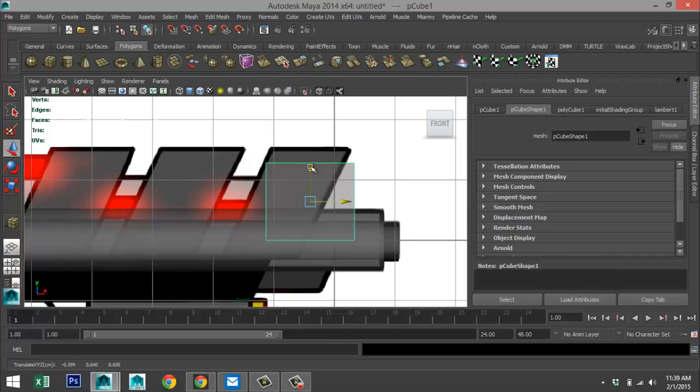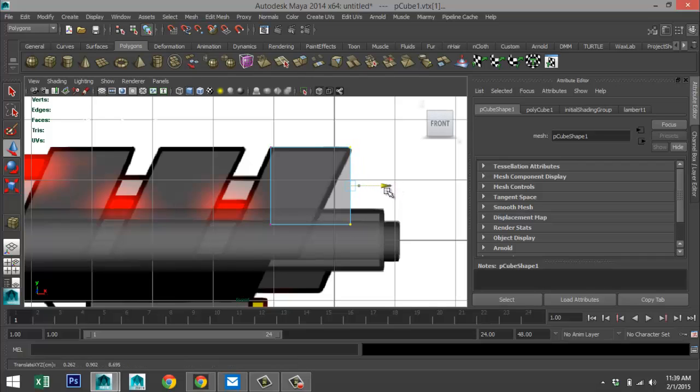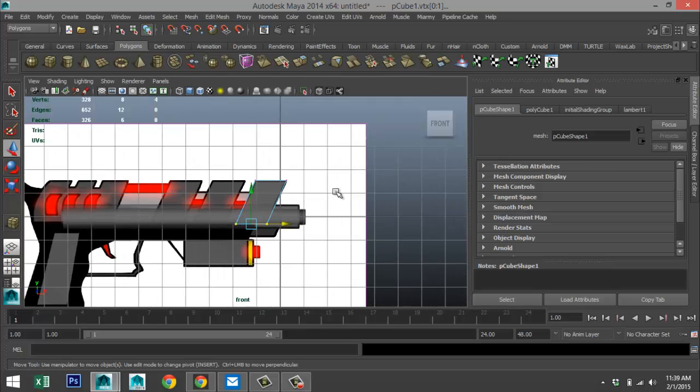So there it is. Hit W. We're going to align that up here, so make sure that corner is fitting. Right click vertex, drag select these two, bring that in until the other one is fitting as well. Drag select these two down here, bring it down, and bring it in until that is aligned. Bit of an odd shape actually, because you would expect it to be a fit. Okay, that looks nice. We do need to deal with the width from the top, but that's okay.